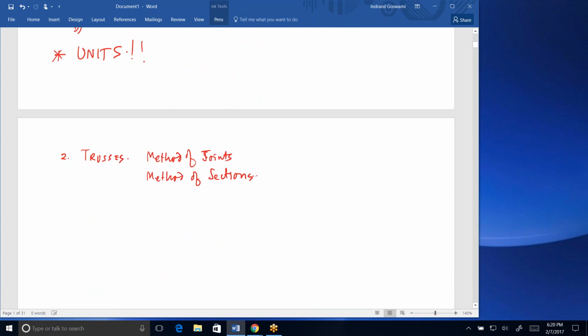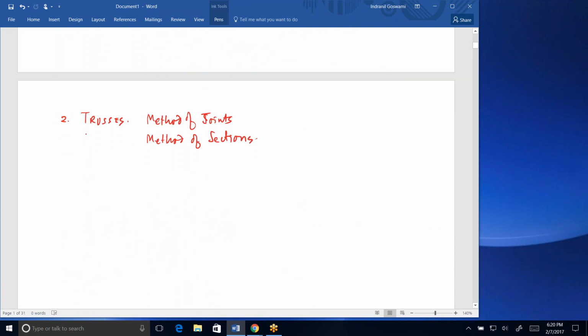For example, here another thing, trusses by definition, all joints are hinged. And so there is another thing that happens for hinged structures, no rigid connections between members, and that is the idea of zero force members. You can identify zero force members for hinged joints without doing a full analysis.